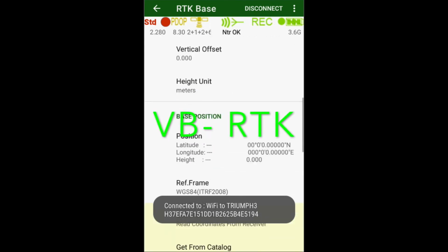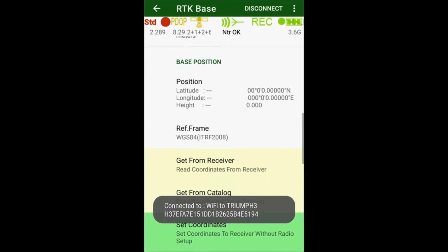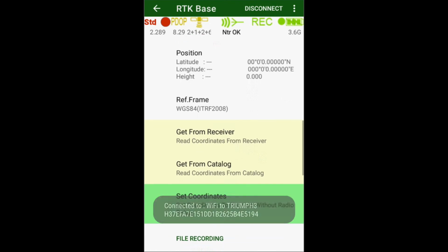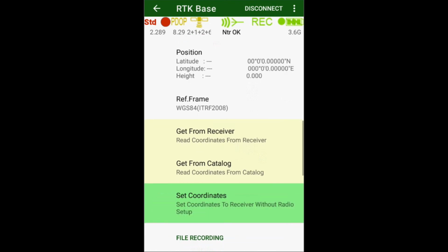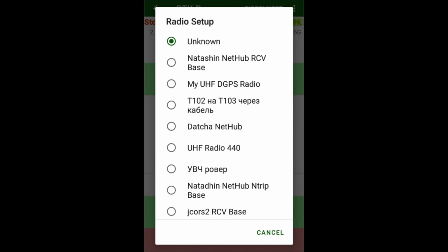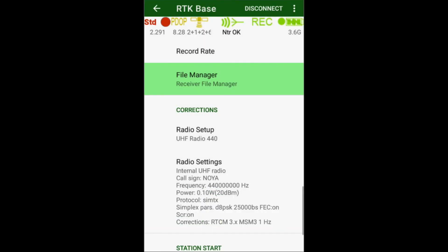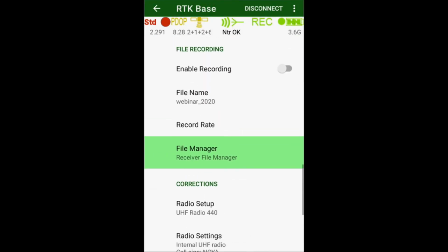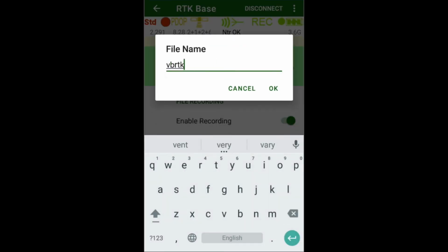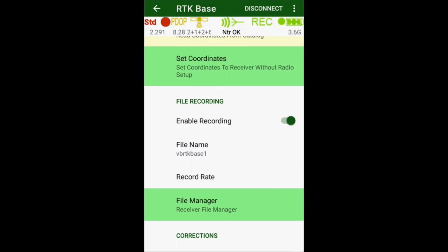Another variant is VBRTK. In this mode we set our own base station. That gives a very short baseline and increases the probability of fix a lot. But usually to start our own base a precise position is required. Not in VBRTK. You can start the RTK base from any open position. It starts collecting raw data simultaneously with transmitting corrections to your rover. And while you survey many short RTK points with the rover, the RTK base collects a long raw file for hours.